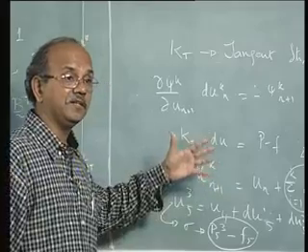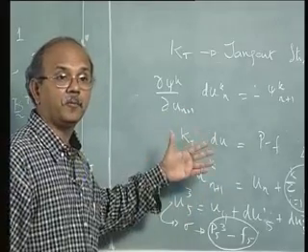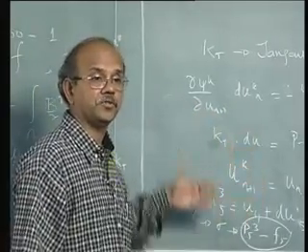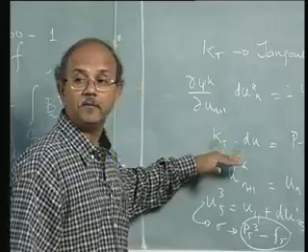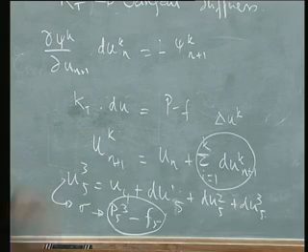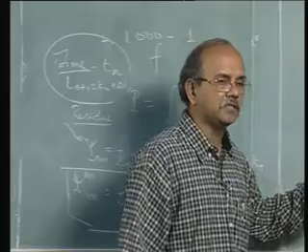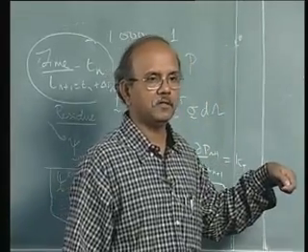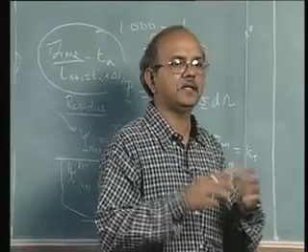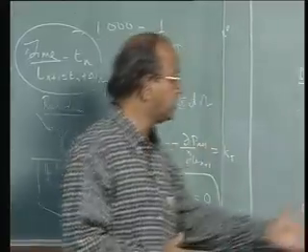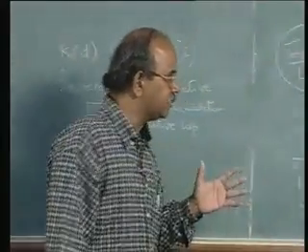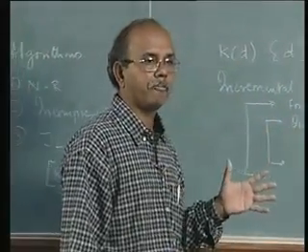Not only an incremental approach, but also an iterative approach. So tangent stiffness, every time you form it, takes time. You can modify it a bit. We will do that graphically, maybe in the next class. We can modify this procedure a bit and call this modified Newton-Raphson. You will understand that once I put this whole procedure for a one-dimensional case in a graphical form.